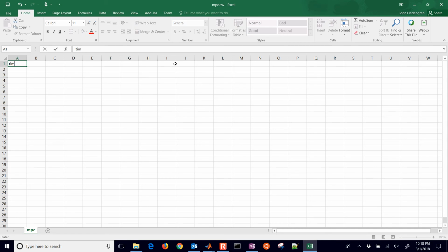Once it's open, I'll just have time, and we'll just do 0, 1, 2, 4, 8, and then coming on down, I'll just fill this down to about 60. So we have a 60-second horizon for our controller. We're going to be running every second, and we have unequal spacing on these time intervals. For the first couple we have 1, and then we move to 2, and then 4, and then it's 4 beyond that. One of the reasons why we might want to do that is because we want to have 1 second cycle times.